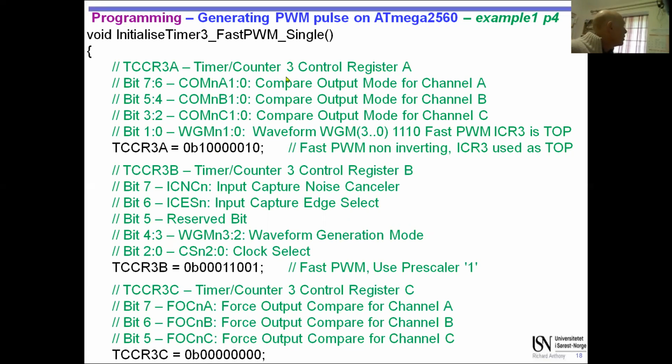So that would mean in bits 0 and 1 here you've got to put this 0, 1, because this is 0, 1, 2, 3. And in bits 2 and 3 here, you've got to put these 2 bits, right? So this is bits 0 and 1, so they would have that part.